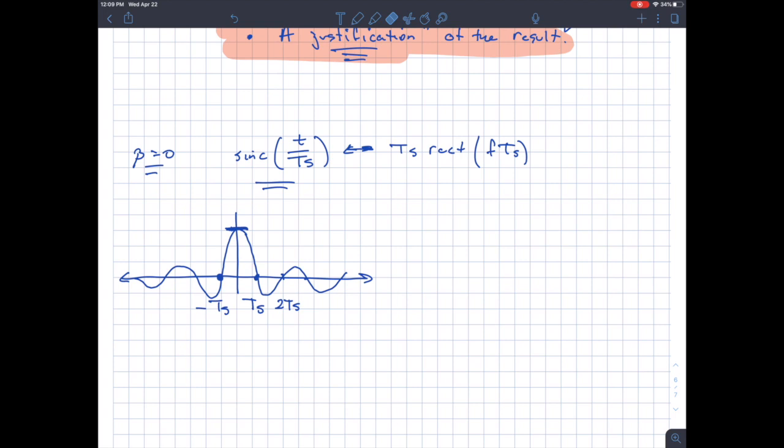All right, so then the question becomes, how fast can you send these through a channel? And what we know is that if you get distortion because of lack of bandwidth, it creates intersymbol interference and impairs our ability to communicate. So what we're going to do next is, this is the time domain sinc pulse, we'll call it p(t), and we'll look at its Fourier transform.